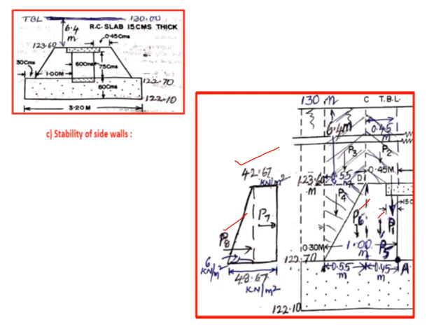So now the moment is calculated about this point. Each of the lever arms you should calculate. For example P1, because it is lying at this, the bearing is 30, so it is 0.15. Similarly for P5, this is 0.45, it is 0.45 by 2. What about P6? It is 0.45 plus one third of 0.55, like this. What is P2? For P2 lever arm is 0.45 by 2. What is lever arm for P3? It is 0.45 plus half of 0.55.